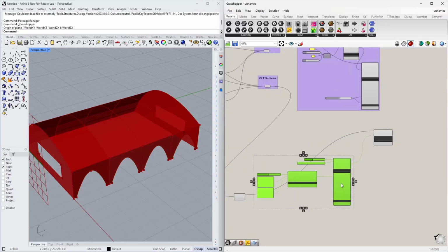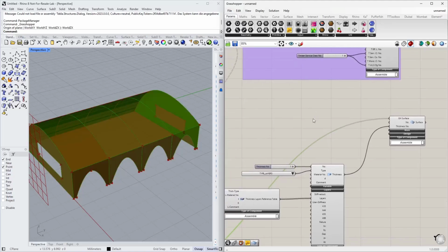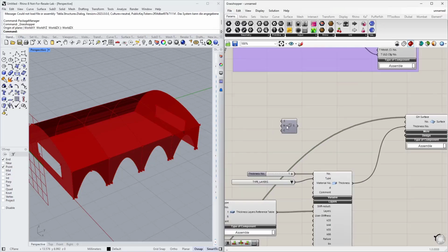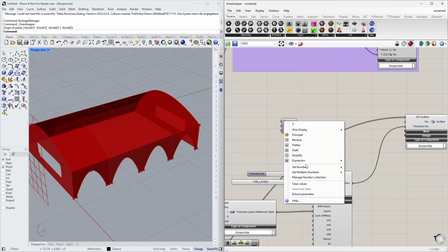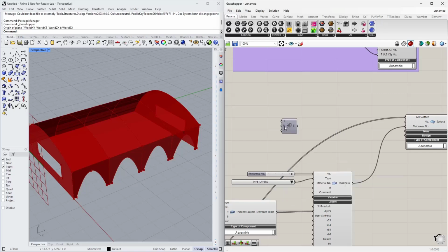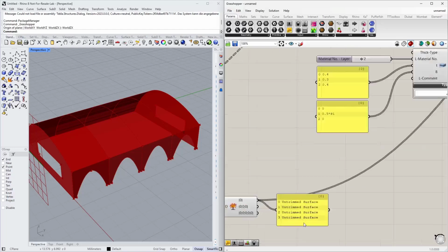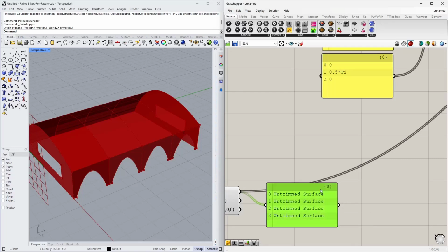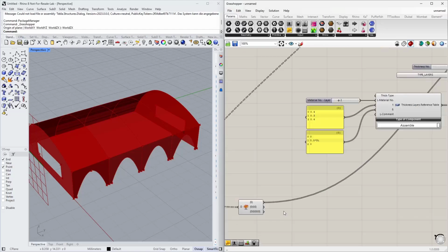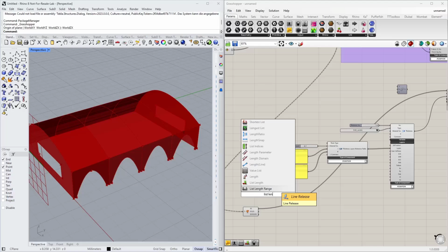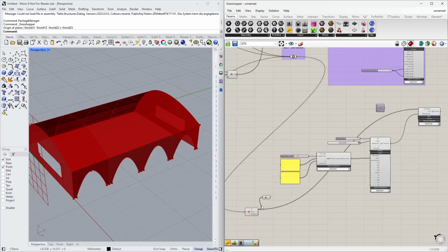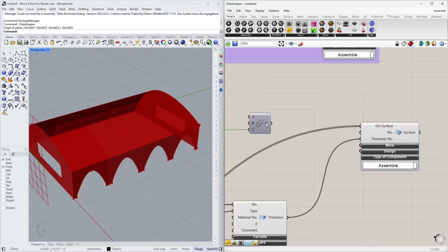The last step here is the numbering. Yeah, as I said, I tend to number all my surfaces, so that can be done with the series component. This index number starts with the value 1. So I define here for the start index number 1. The step is of course 1. Yeah, 1, 2, 3, 4, and the amount of index numbers that I need is linked to the length of this list. Yeah, I have here 4 surfaces inside, depending how many copies I create in my Grasshopper algorithm. So the length of that list is basically the amount of copies that I need. So I can count the lengths with the list length component and connect it here to the amount of copies. And now I get a list of 4 index numbers, 1, 2, 3, 4. That's what I need for my surface. All right.